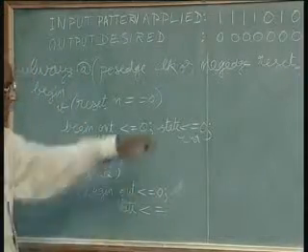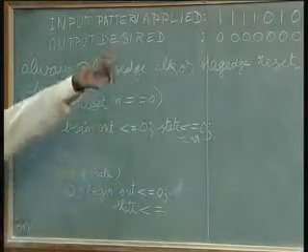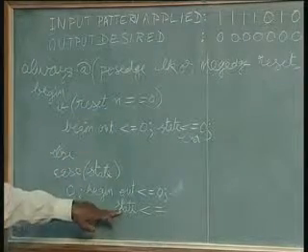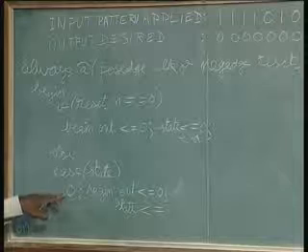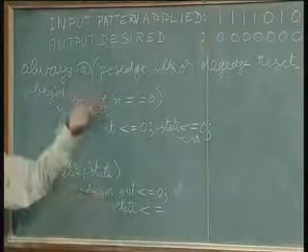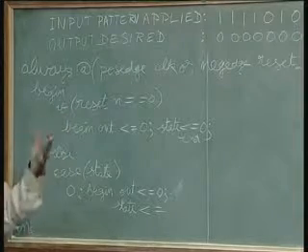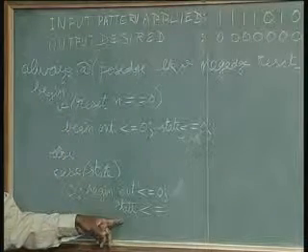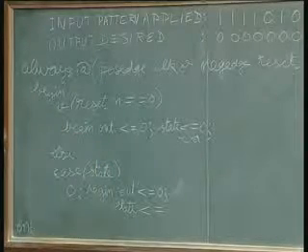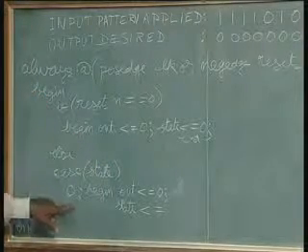Now let us see. It all depends upon the input condition, right? So this is actually when you enter this, we are in state 0, but what you are going to write here is the next state. From this state, where do you go to? That state is what is implied here, and that will take effect only with the arrival of the next clock. With the present clock arrival, we are here.